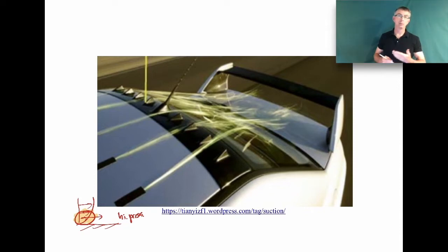And that gives rise to what is known as boundary layer separation, a topic we'll cover in a couple of lectures. So what the purpose of these vortex generators is they swirl the flow around. You can sort of see that they'll swirl the flow around here, and they'll take this high momentum air and mix it in with the low momentum air next to the surface, and thereby re-energizing or putting more momentum into that boundary layer flow very close to the surface. And once you have higher momentum, then you can move further into a high pressure region. And so that's what the purpose of these vortex generators is, they'll put additional momentum into the flow right here.